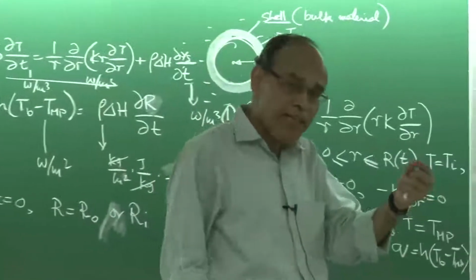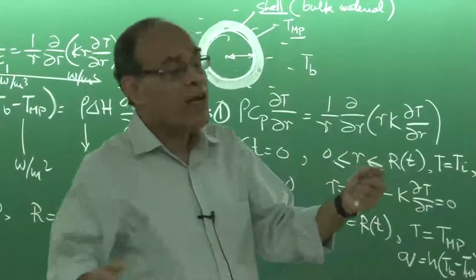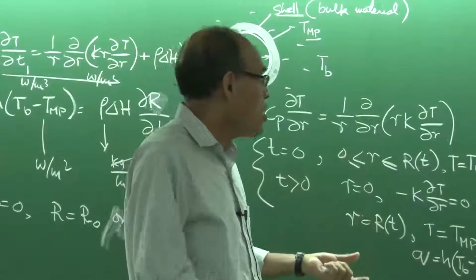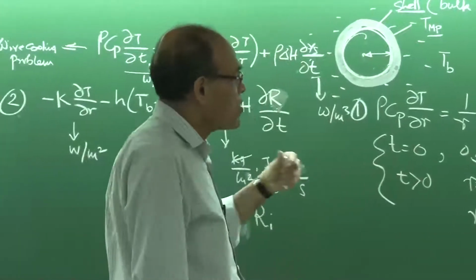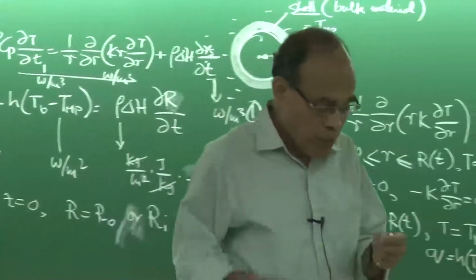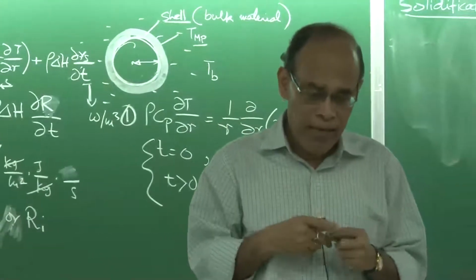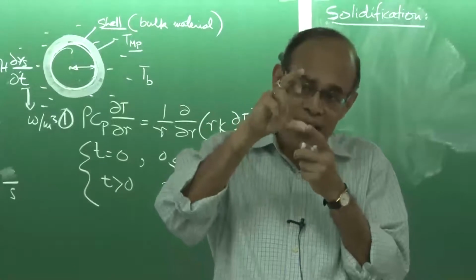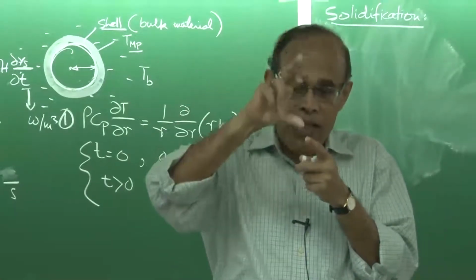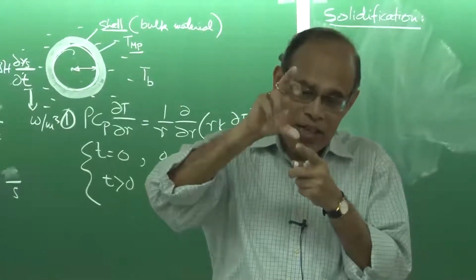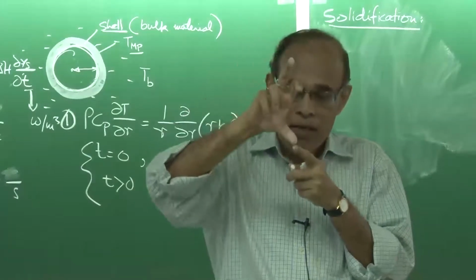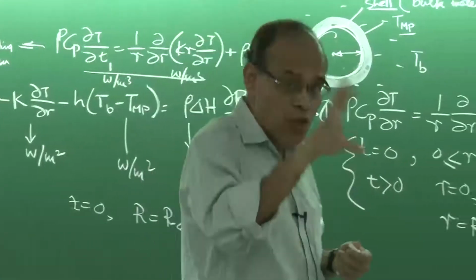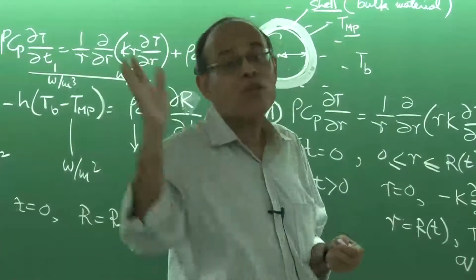And from the solidus temperature itself, the temperature can further go down, the casting can cool while it is within the mold itself or outside the mold, and as a result the temperature continuously decreases. So in a solidification problem, typically superheat is first removed. Superheat means the heat above the liquidus temperature, corresponding to that delta T which differentiates the liquidus temperature and the actual temperature of the liquid. So m c_p delta T represents the superheat. So it removes the superheat first, and once the superheat is removed, then the solidification process starts.